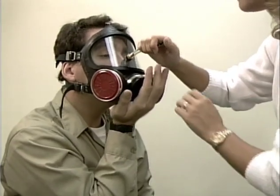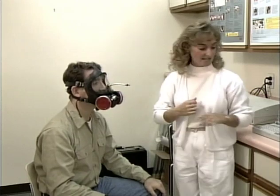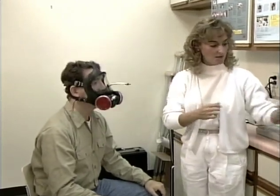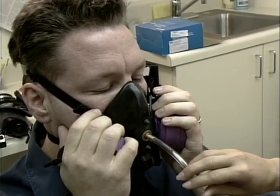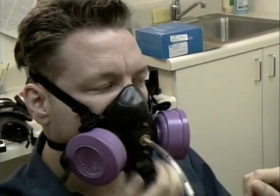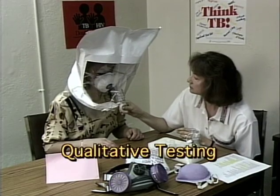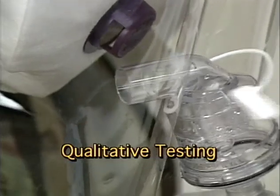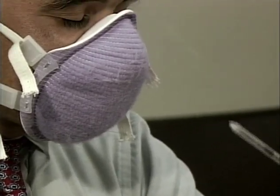OSHA also requires all employees to undergo a formal fit test before they wear a respirator. Fit testing ensures that the respirator really does fit tightly against your face. There are 2 types of fit testing, qualitative and quantitative. Qualitative testing uses scented chemicals or smoke sprayed in the air. If you can't smell them, you probably have a good fit. The problem with qualitative testing is that it is subjective, since it relies on each person's sense of smell.